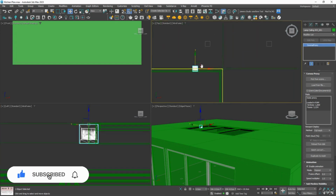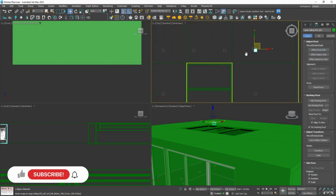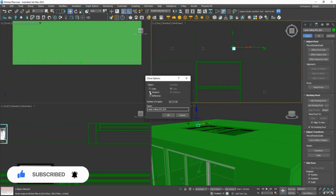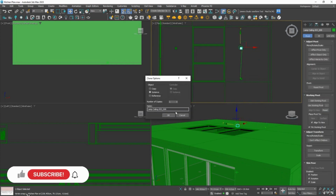And then in the top view, we do actually want these to snap. So again, we'll go to Hierarchy, Effect Pivot, press S to turn on snaps, and we'll snap that to the top left. And then we should be able to easily snap these into position. Holding Shift, we can make an instance, as I don't think the lights will be changing too much. And I'm actually going to create 3 copies of that. And then holding Shift, I'll pull this one down, make that an instance, and same again over here. Great, so we've got some lights in our scene.